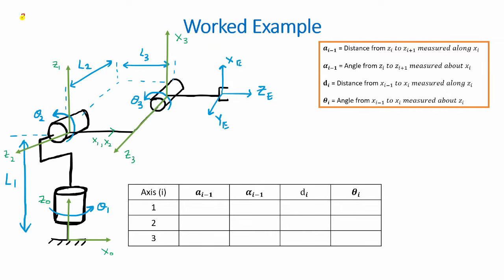Alright, so the second step would be to find the DH table using our 4 link joint parameters. Here, when considering the axes, we move from one to the others. So we would go from 0 to 1, 1 to 2, and 2 to 3. Considering the first case, 0 to 1, for the first two parameters, i would be equal to 0, and for the next two parameters, i would be equal to 1.